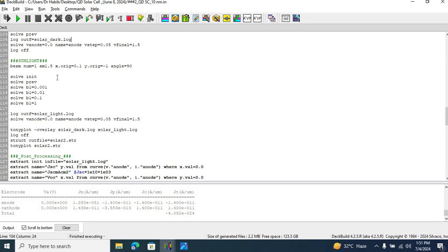So the solar spectrum typically extends from the infrared region to the ultraviolet region with the wavelength range from 0.2 to 3 micrometers. But the intensity is not uniform. The path length of the light in the atmosphere depends on the angle, which will vary with the time of the day. And this is given by air mass number, which is secant of the angle between the sun and the zenith, or the vertical direction.